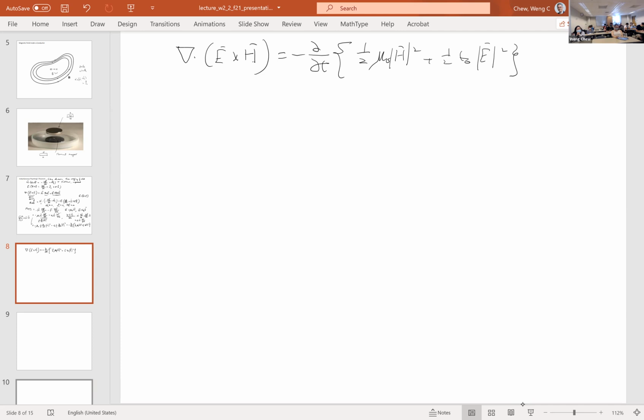The current continuity equation says the divergence of J is minus dt rho. And we mentioned previously that the current continuity equation has the concept of charge conservation. Left-hand side, J is current flow. Right-hand side, rho is charge density. So here we see the same thing. Left-hand side, E cross H, we just convinced ourselves that that is power density, which is like power flow per unit area.